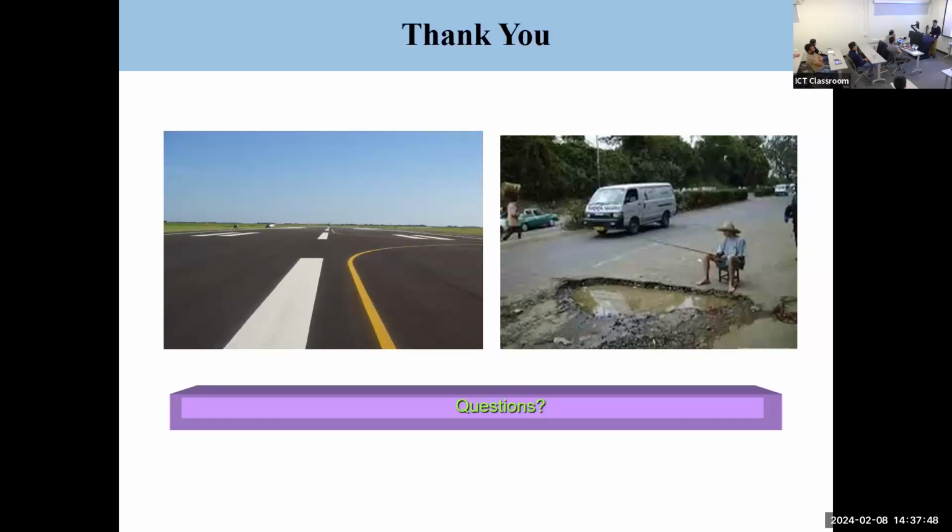For the criteria, there might be other criteria, but I think something like Drucker-Prager has some of the fundamentals in it. First of all, some of the parameters, for example the slope of the line, are related to the angle of friction of the aggregate, so that captures that. It is pretty obvious that our material is very susceptible to confinement level.